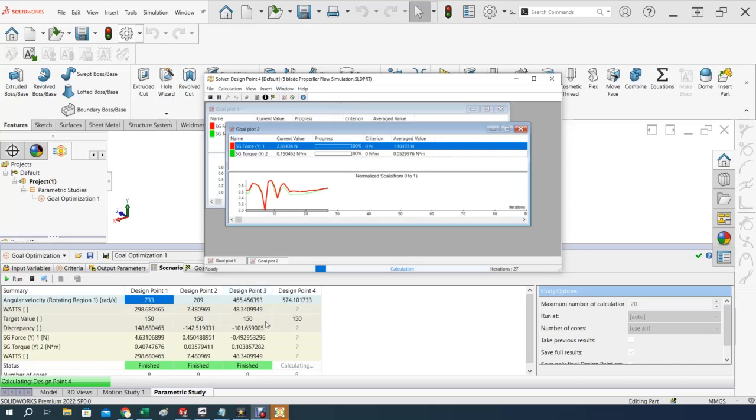It's running right now. And how about the force? Kind of weird. Got a negative value here. That's kind of strange, meaning that the resolution that I'm using, which is 5, might need to be increased to 6 or 7, just to ensure the numbers start to make sense. We'll see how this looks at the end, but definitely I need to improve something on the force here.